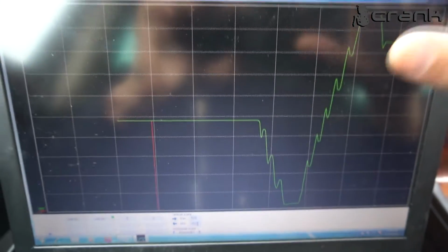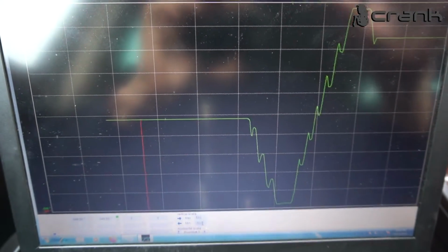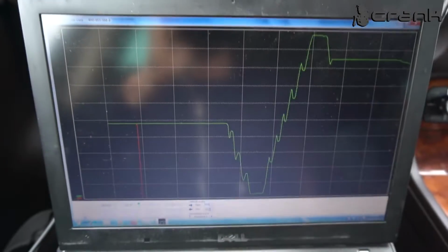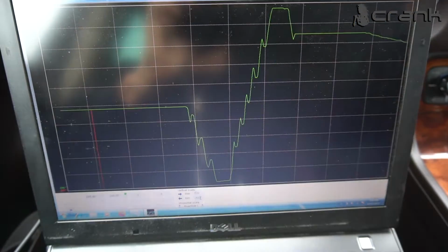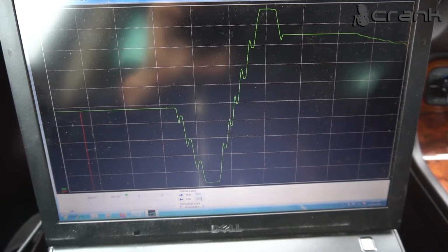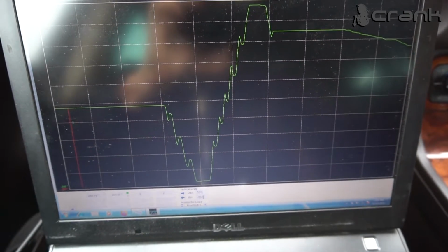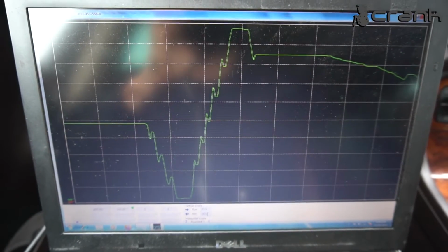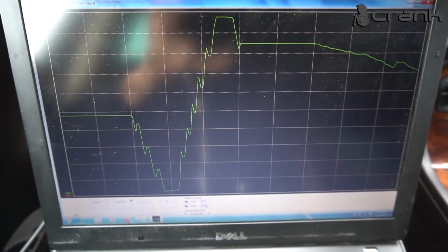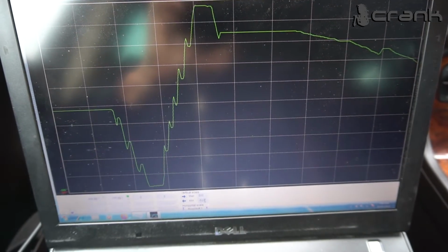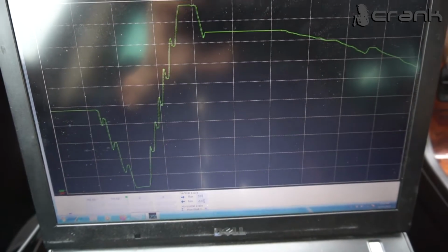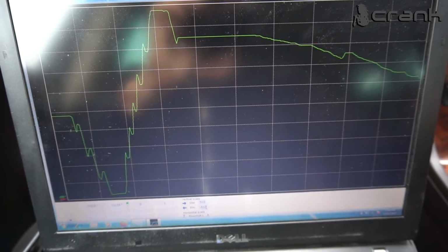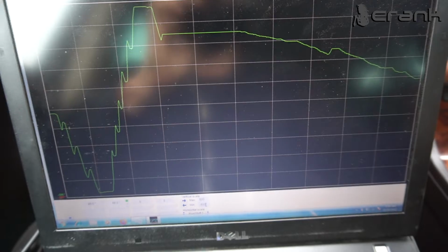So to be sure that we have an issue with the steering angle sensor, now I'm going to rotate the wheel really slowly, and we're going to check for abnormal behavior while I'm doing this. You need to do it relatively slowly, because this is going to help you much more easily capture the issue, if there is some kind of issue, of course.